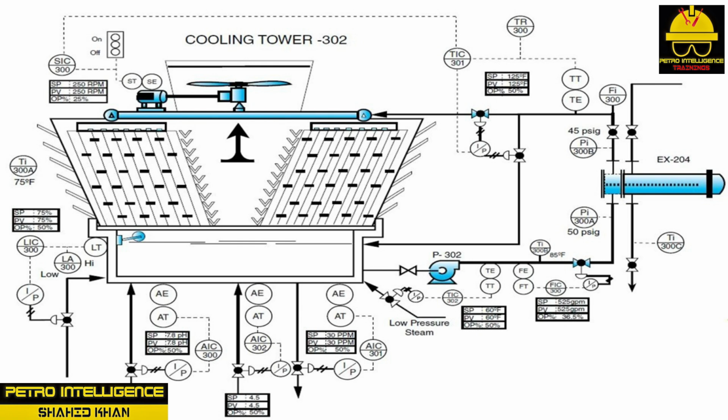Blowdown is closely related to the term concentration cycles. Blowdown refers to automatically removing 7 to 10% of the water in the water basin and replacing it with fresh water. In most cases, the water makeup system runs continuously due to evaporative losses, drift losses, and draw-off. The concentration cycles in CTW 302 are set at 6 concentration cycles before it blows down the system. A cycle describes one pass from the cooling tower to the process and back to the cooling tower. Cycles of concentration display the accumulation of dissolved minerals in the recirculation system.